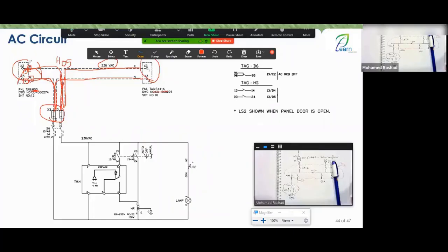So this means that he exited from here with this MCB, with the red phase and neutral only. I mean, yes, you have this bus bar as 3-phase, but this MCB is 2-pole, guys. So let me enlarge this. Again.